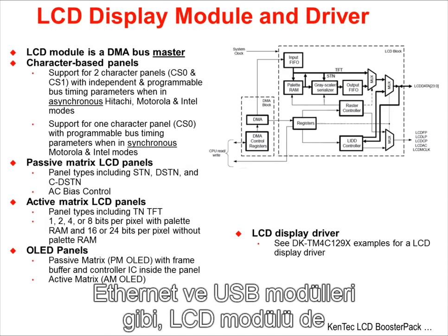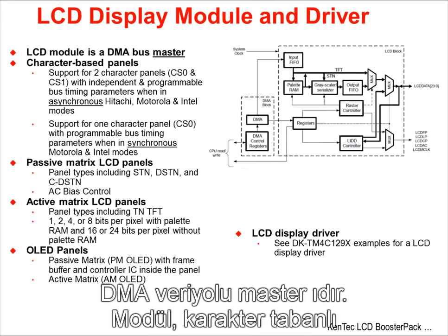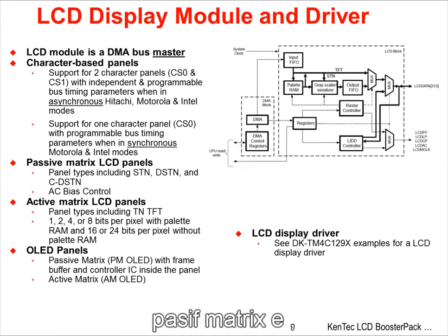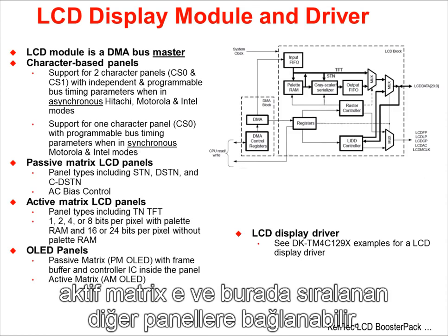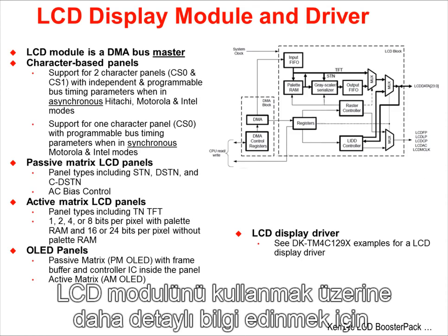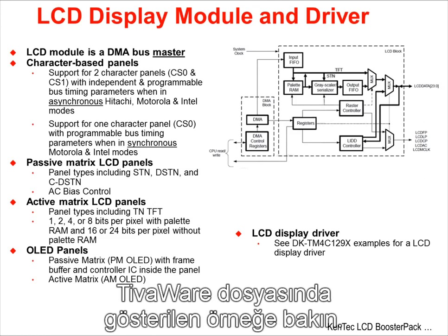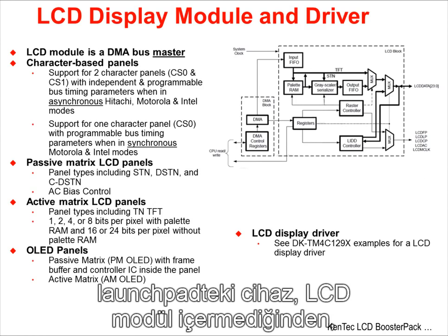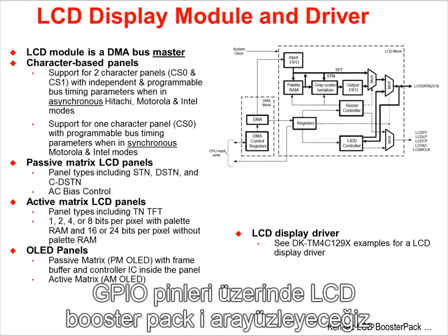Like the Ethernet and USB modules, the LCD module is also a DMA bus master. The module can connect to character-based, passive matrix, active matrix, and OLED panels listed here. Take a look at the example shown in the TivaWare folders for more information on using this LCD module. Since the device on the LaunchPad does not have an LCD module, we will interface to the Booster Pack LCD over the GPIO pins.